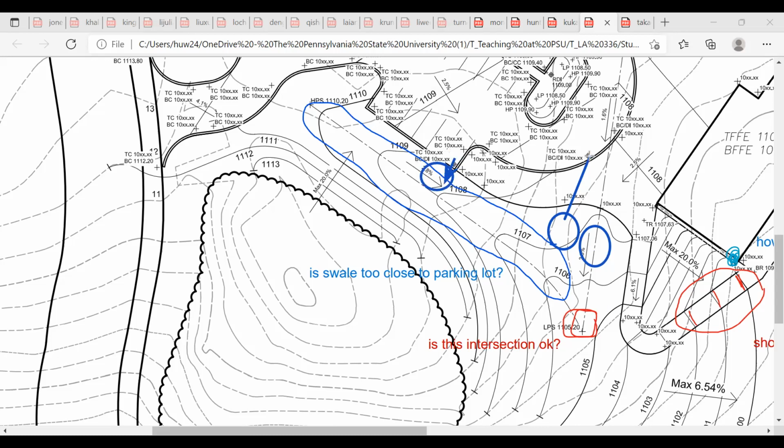So that's that. And this one would have two lines and a TD to indicate that's a trench drain. This one will be surface flowing into the cell, doesn't need a curb or anything. It just needs no curb spots and high point, low point, and contours.